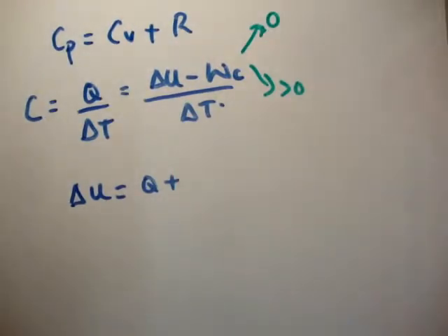Now, anytime I say constant volume, I'd like you to actually sit back and think of a closed system. Think of a closed box. If the volume of this box isn't to change, the only way I can add energy to it is by heating it. I've reduced the number of ways I can add energy to my system by quite a large amount if I can't compress it. Alright?